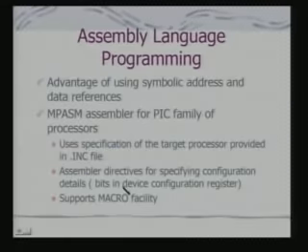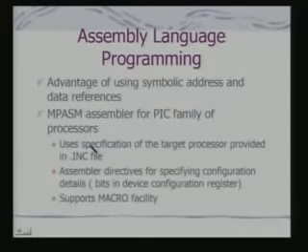Also, there is a device configuration register. The device configuration register programs your processor in a variety of ways, and this configuration information is also to be provided. In fact, these two features are nothing exceptional for PIC, because you will find when you are using assemblers for a family of processors with various target applications, you need to provide information about the configuration of the processor and specification of the target processor for assembling or translation of this code.